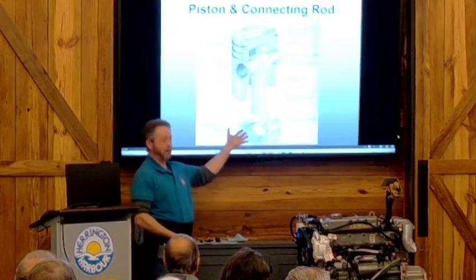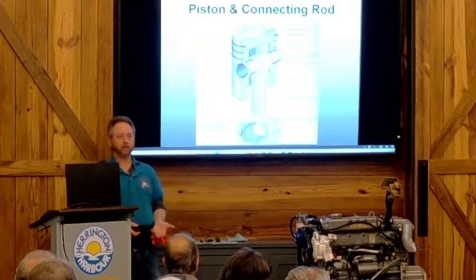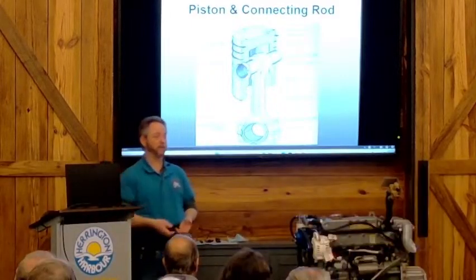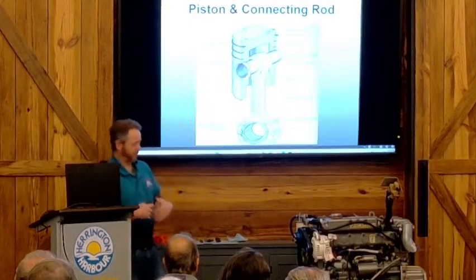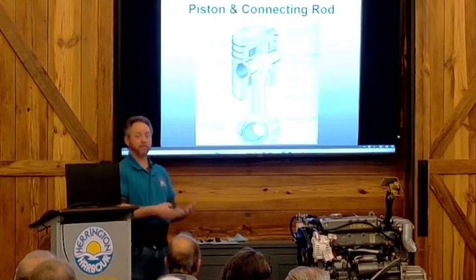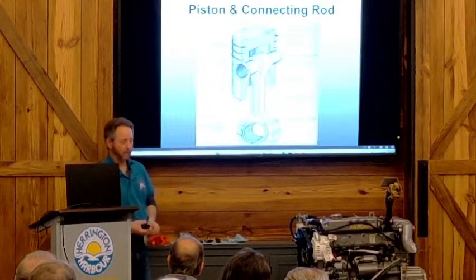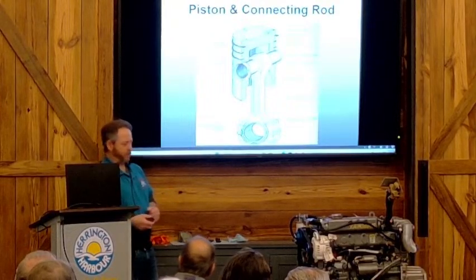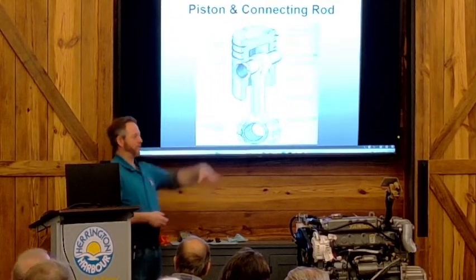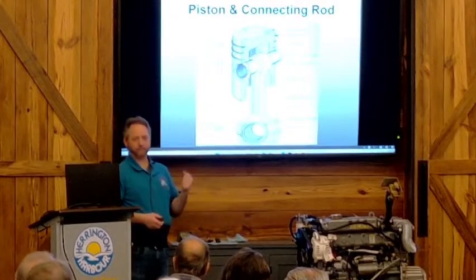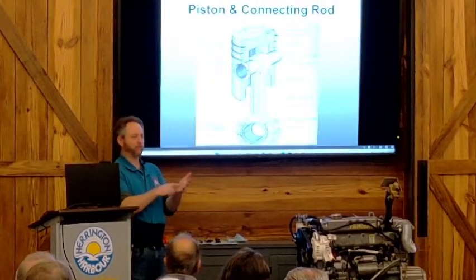To protect these bearings, we change our oil on a regular basis, and we use a higher quality oil. So when we do oil changes, we've got to make sure we buy diesel rated engine oil. You can't just go to the store and just grab 15-40. You've got to look at the back of the bottle and make sure it's rated for diesel engines.